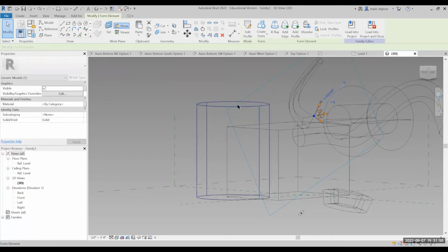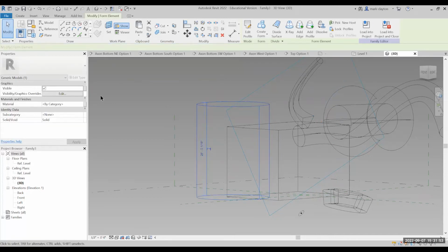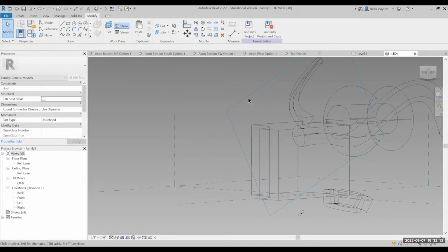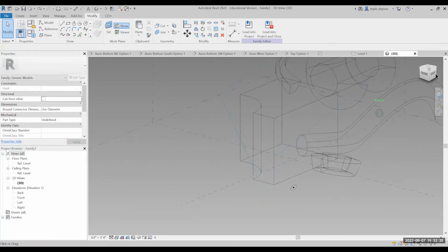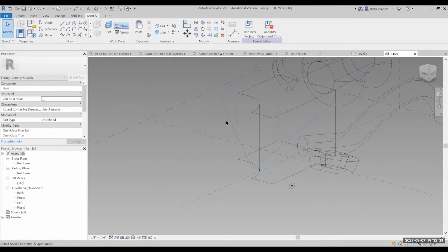So if I pick this cylinder and over here, I simply pick this property, I can change it to a void. Did I change it to a void? Is it working? Yeah. So it sliced away the element there, the part of that box there. So you could use any of these to start carving away that basic box, manipulating it in different ways.